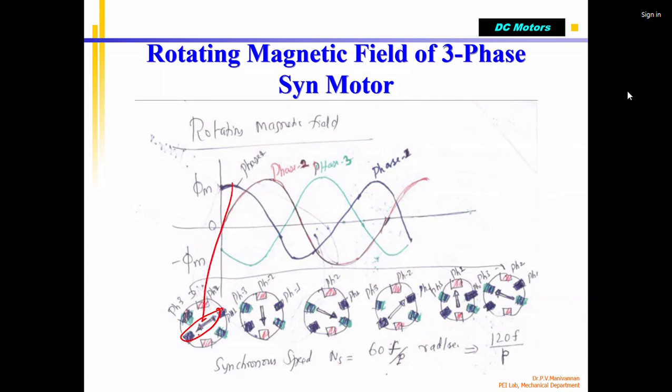But please note that it is continuous, not a step. It is varying. This voltage is decreasing, this is increasing. As the resultant, at this time instant, if you consider phase 2 becomes maximum, the rotor has rotated so many degrees and aligned like this. Then the green phase again, rotated from here, it aligns. So when I give 2 cycles, automatically my rotor has rotated 360 degrees.